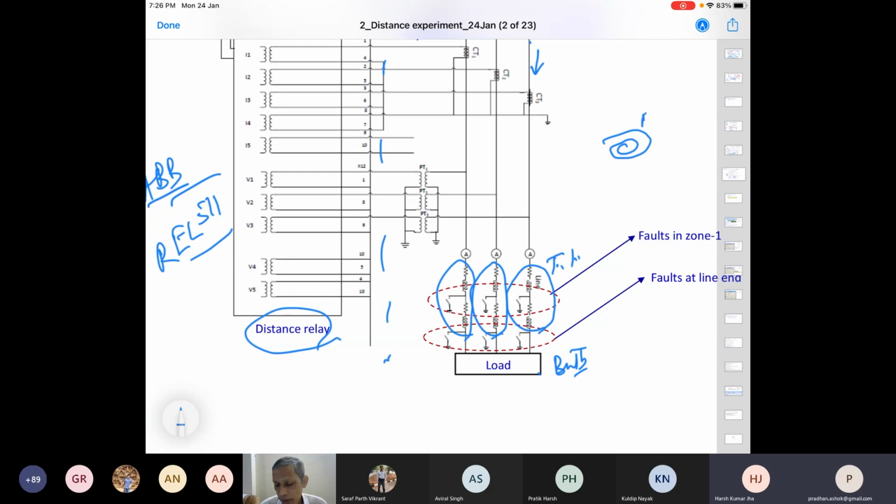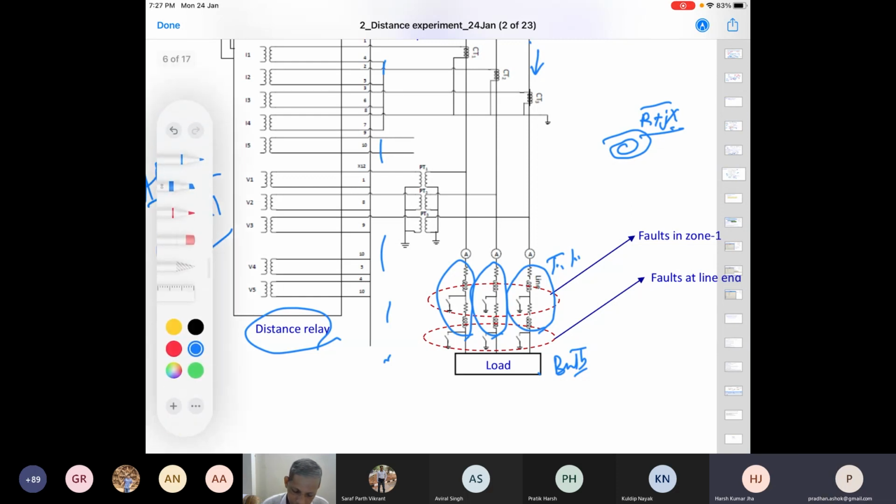You can see that the coil has a resistance and inductance. So it emulates the corresponding transmission line. Very similar to that, this wound inductance is achieved such that we get an 80-85 degree kind of impedance angle. And the parameters of the line are known to us, because the inductance and the resistance values are known to us.